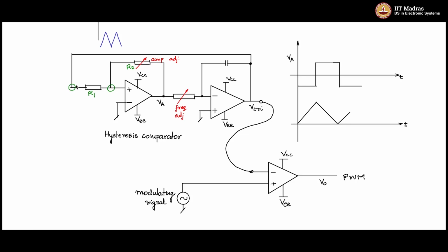And this is one source which we need to superpose, and this is the other voltage that we need to superpose to obtain the value here. And let us say that we will obtain the value at this peak. This is what we want it to be, 1 volt here at this peak value. At the time corresponding to this value, this is at minus 15 volts or VEE.